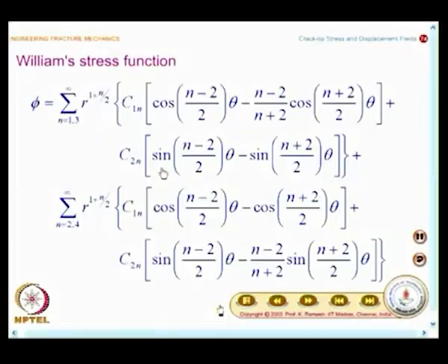You have to look only at the crack face displacements. The far field loading is secondary. So once you take up a multi-parameter solution, from now on we will have to say take as many terms as would satisfy your problem under consideration.